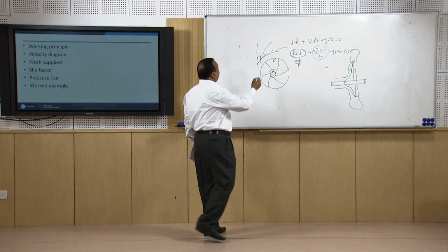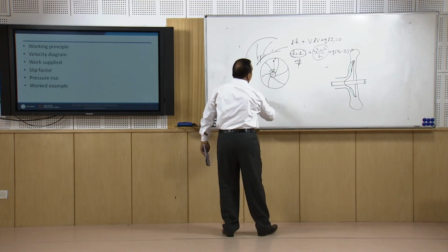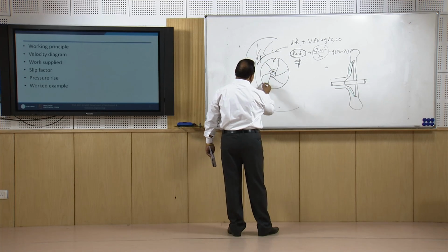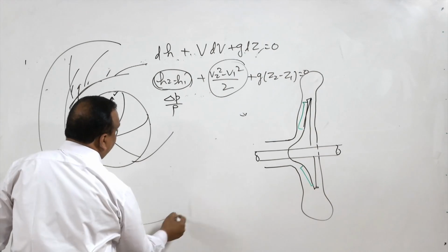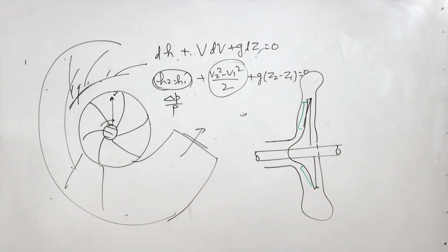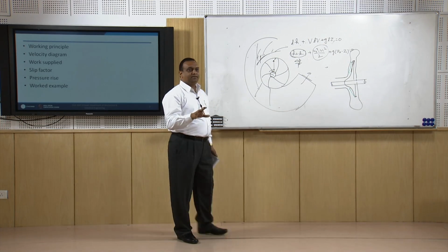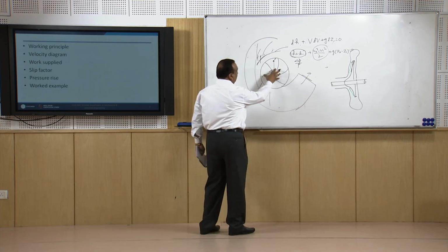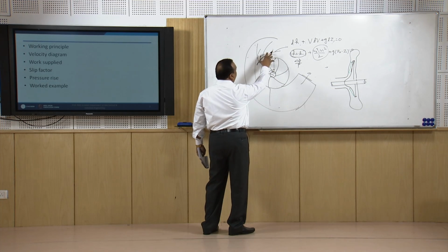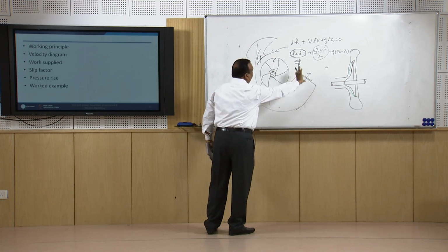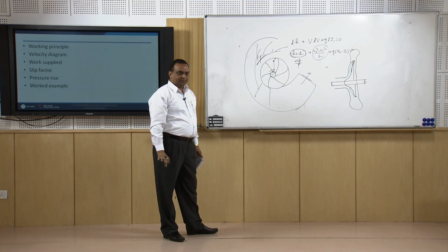And after the vane diffuser, there is a volute casing of increasing cross section, and at the end of the volute casing, there is the exit. So, in a nutshell, initially the air is sucked into the compressor, and kinetic energy is imparted by the impeller. Now, this kinetic energy is converted into pressure energy in the vaneless diffuser, vane diffuser and volute casing, and it goes out of the system.